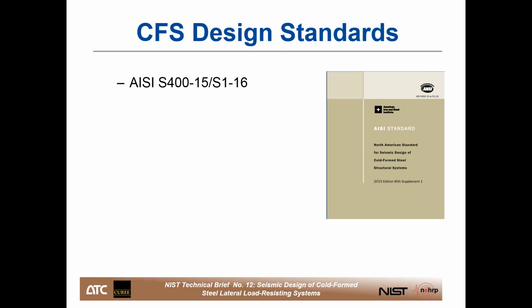So the AISI standard most relevant to technical brief TB12 is S400, the North American standard for seismic design of cold formed steel structural systems. TB12 happened to be based on S400-15 with supplement number 1, or S400-15/S1-16. So S400-15 combined the high seismic provisions of S213 and the special bolted moment provisions of AISI S110.